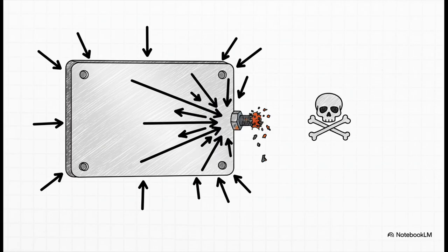If you have a massive surface of a noble metal, the cathode, and you connect it to a tiny piece of an active metal, the anode, all of that corrosive energy gets focused on that one tiny spot. Imagine a huge stainless steel plate held on with one little steel bolt. That bolt is going to dissolve at a terrifying rate. You absolutely have to get this concept. It explains so many real-world failures.